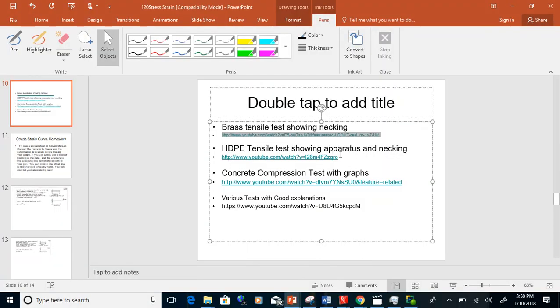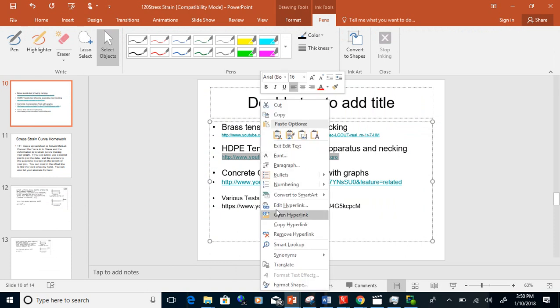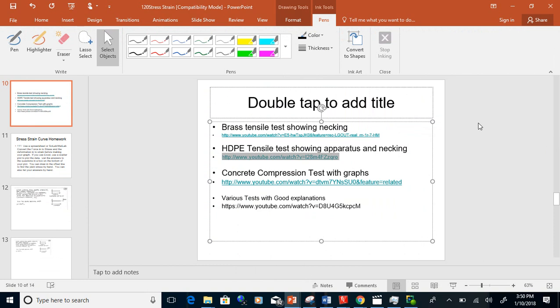Yeah, pretty much. But those machines are quite strong. I mean, they're just taking steel and tearing it apart, basically. Yeah, seriously. So, maybe this is a little bit too much detail, but how does the machine not jump and snap? Yeah, the machine doesn't jump and snap because the machines generally are set to elongate at a constant rate. Not to exert a constant force, but to elongate at a constant rate, which is one of the reasons the force jumps around a little bit. Usually hydraulically, actually. They have a flow control valve.